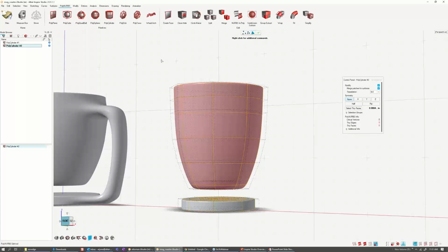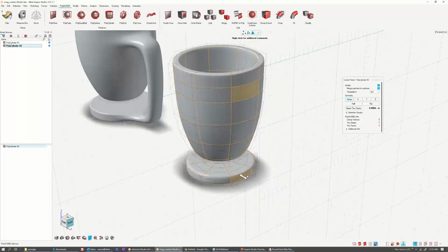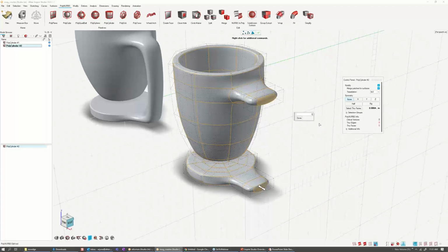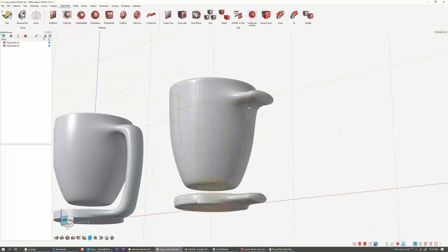So now when I repeat the same operation that I did earlier, holding both of them, Control and dragging, it should work as expected because the normals are now unified, or the same. So I'm going to extrude it twice by about an inch. And now I have these two parts that can be easily bridged using the bridge command.